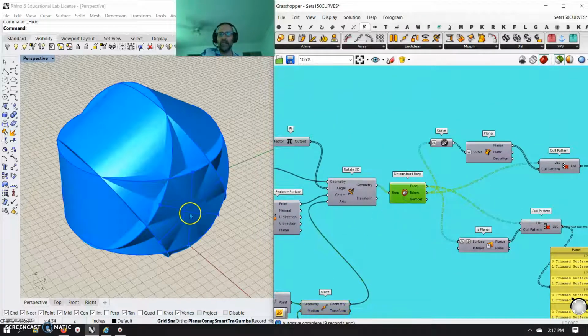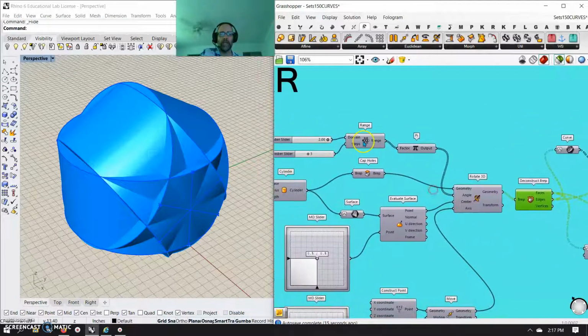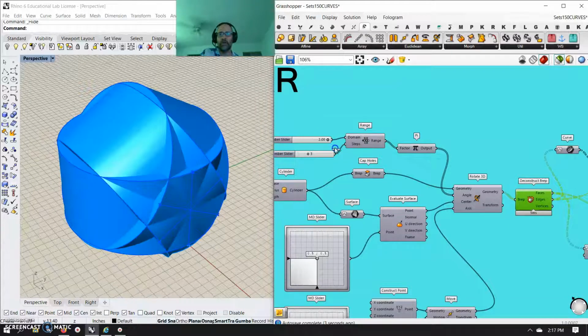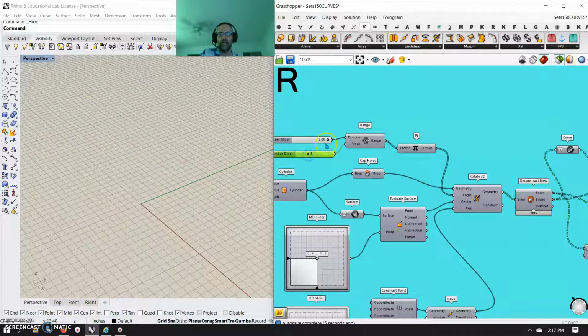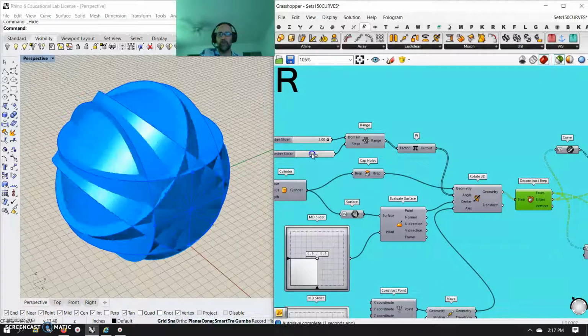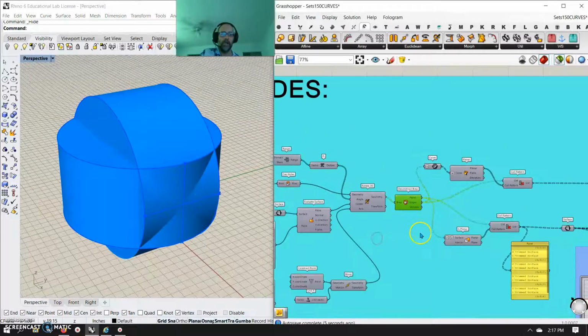And then I deBrep that surface, and what I do in doing so is, because I've deBrepped it, because of this angled range, I've run through 2 pi, which I can bring back to 0, but I can rotate it around to 2 pi, which is nice, and I can do that as many times as I like. So as I have a Deconstruct Brep, I can do as many as I want. I think I'll just start low. Let's do a 4 count, see what geometry is built.